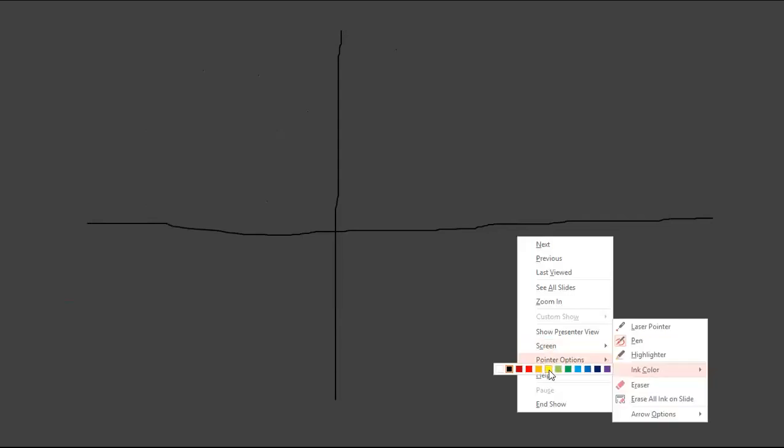So you can draw it according to this, right? Sigma 1 is 13 point something, right? Let's say it's here. So sigma 2 is 11 point something. So you know principal stress occurs where the shear stress is 0, right? On that plane, right? Sigma 2 and sigma 3 is minus 16 point something.